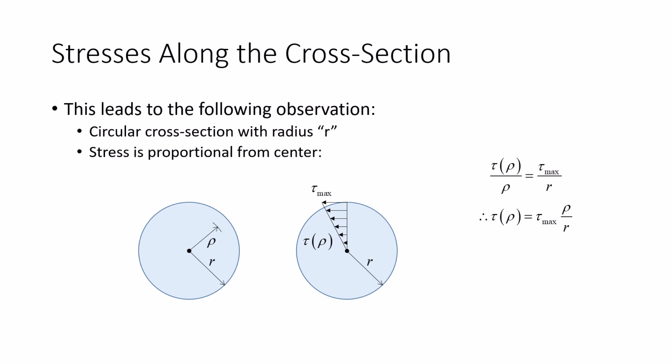It's the same stress everywhere, right? But with torsion, that's not the case. As an engineer, if the stress on the outside is within limits, then you're good. So that's going to be something that's going to start to creep up. Not just what the stresses are, but where are they occurring, okay?